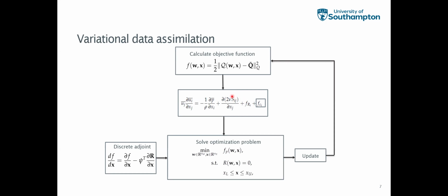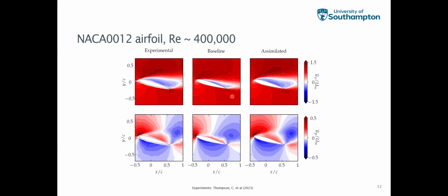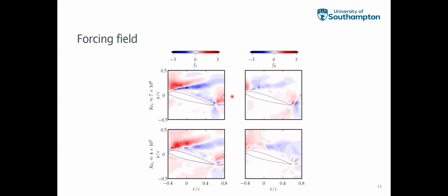I do have a quick question in terms of adding this force term into the momentum equations. In a slide you showed that the range of the force term is -3 to 3. You also mentioned you somehow normalize things, because I would imagine that the range of this force term will be very different depending on which case you run, depending on the velocity magnitude, depending on the geometry and such. How do you normalize it such that it's within a small range? Is this -3 to 3 the upper and lower bounds you prescribe when you do the field inversion optimization?